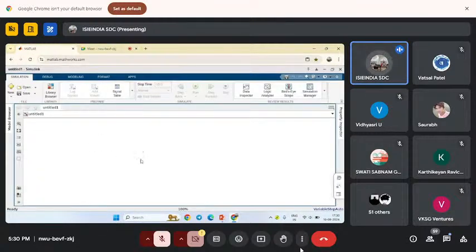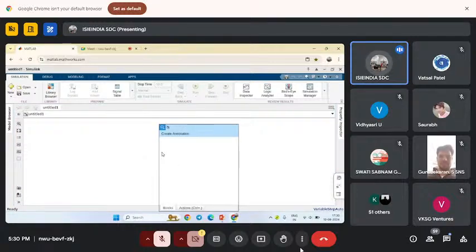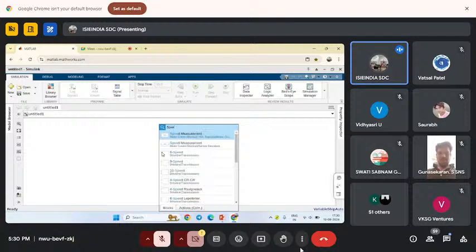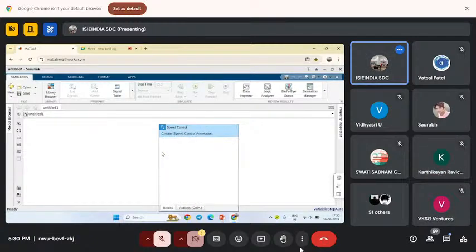Yeah, first of all we will go for the motor. In Simulink, you can access the libraries. A number of blocks will be there, so you should know what block you need to use. Here I am doing the speed control of a PMSM motor by using a PID controller.